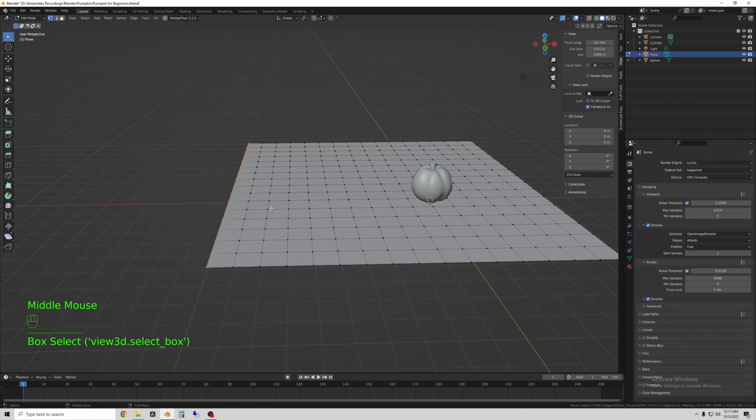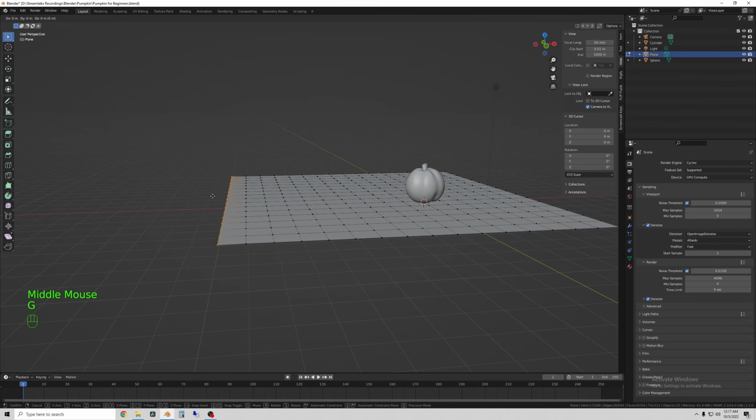like that. And then we can hit G to move all of these, and then lock it to Z. We don't really want to do this for 3 or 4 different lines of vertices. It takes more time. So with these selected, we can use the proportional editing button. It's right here in the middle of the screen.